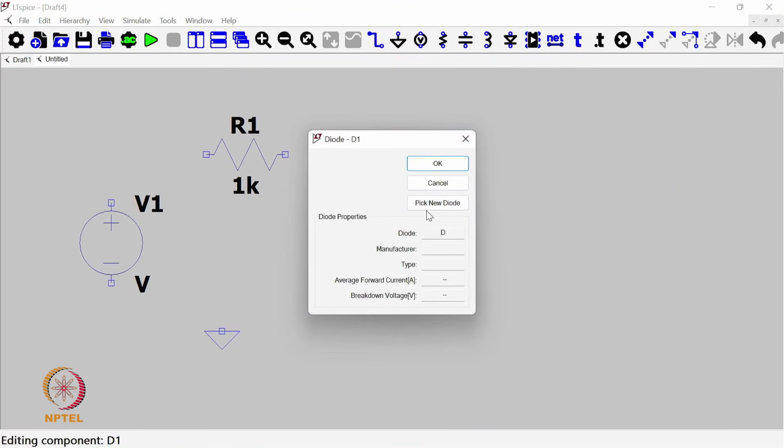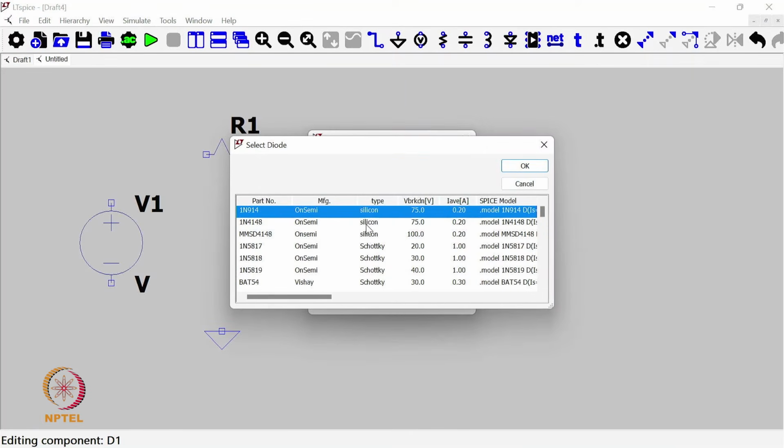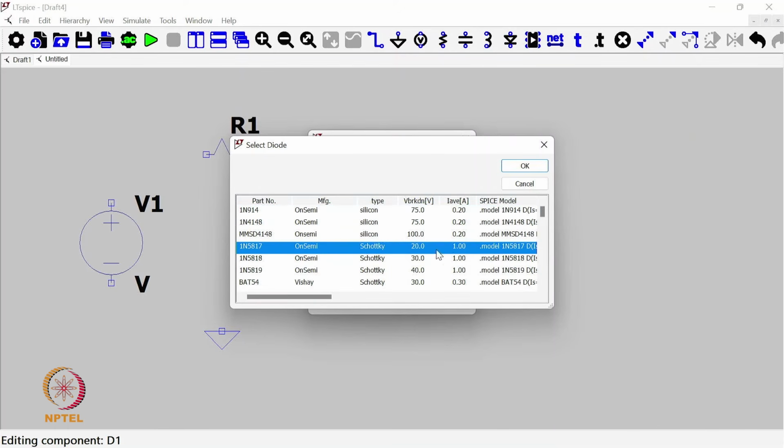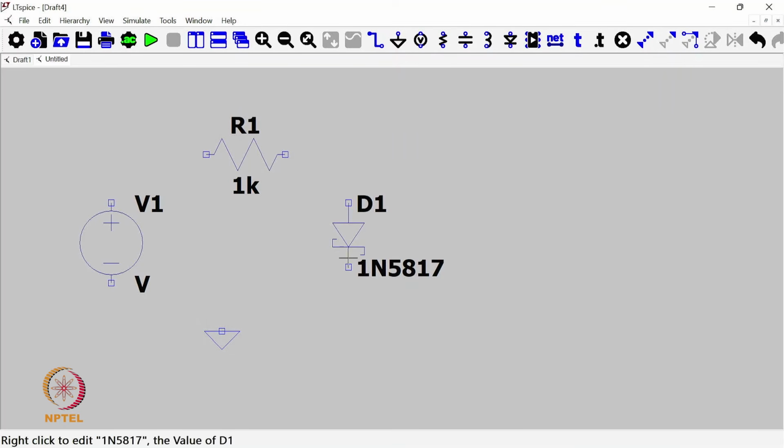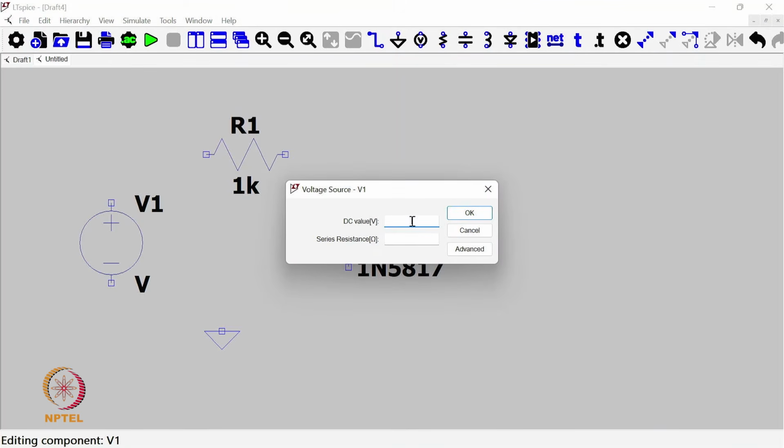Diode, let's say we take a realistic diode model which is developed by Linear Technology. For the value of the voltage source, we can even have a fixed value, but we want to calculate the complete characteristic of the diode. It means we need to sweep the value from a very low value to a very high value. So we have to make it a variable.